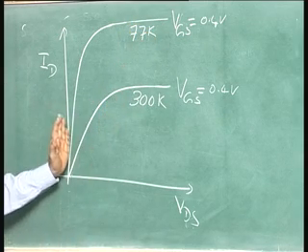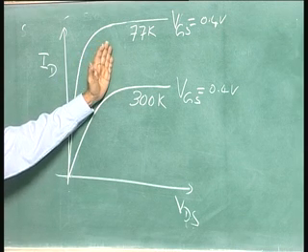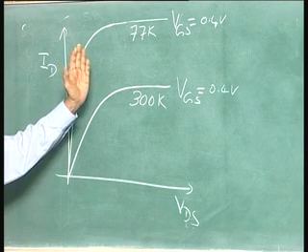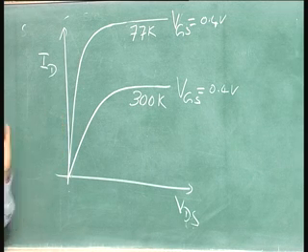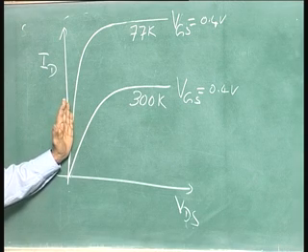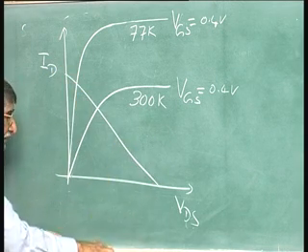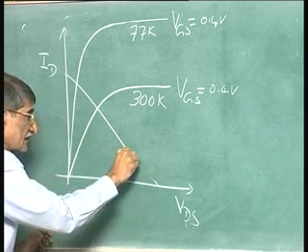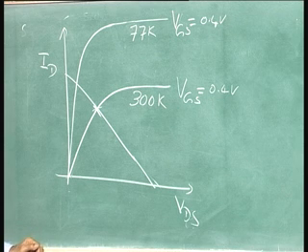You can see the benefit here. Not merely do you get better transconductance, you also get a smaller on resistance. For digital circuits, it is really required; you want the on resistance to be smaller. Just see here, if I put a load resistance like this, for the same gate voltage you will end up here in the on state, whereas here you will end up here.